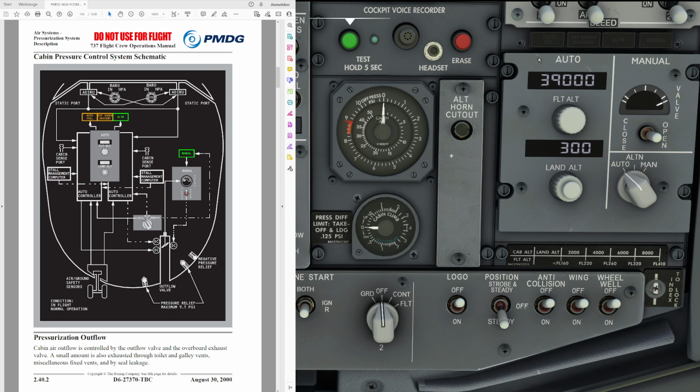Now, the pilot is going to enter the planned cruising altitudes into the panel, and there are two different philosophies over here. Most pilots would enter the first cruising altitude that you plan to climb to, and disregard any step climbs. The reason behind that is that you would not accidentally activate the off-scheduled descent function if you don't execute the step climb that you have planned for later on.